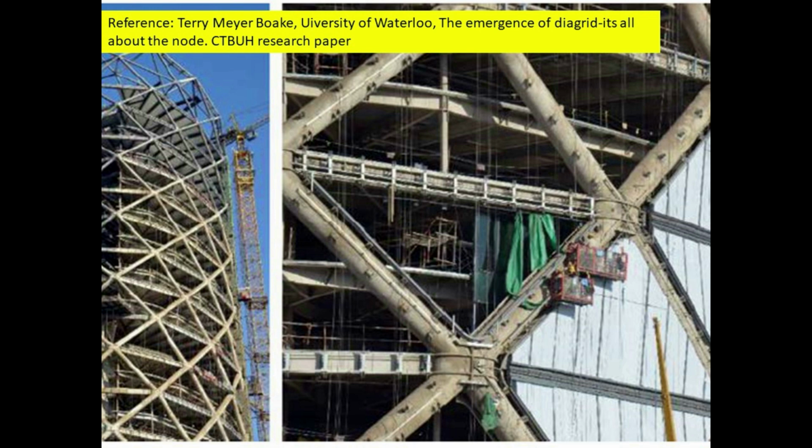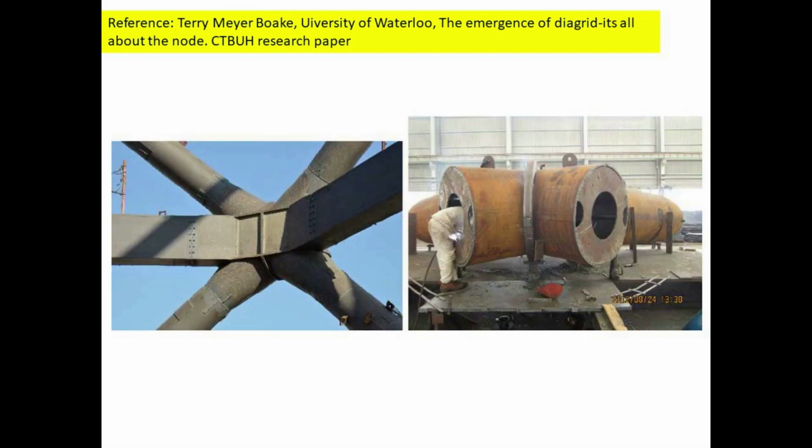This type of system requires all-welded connection, both for stability as well as to seal for leakage. It is necessary to have continuity of the void. This is for pumping of concrete through the node. At the left figure, the node is seen to be site-welded to the incoming diagonal members. To resolve this, custom tapered tubes are fabricated between the tube and the plates at the intersection. At the right figure, the node is in the fabrication shop. Reinforcing at the connection of the node to the tube permits the passage of concrete.